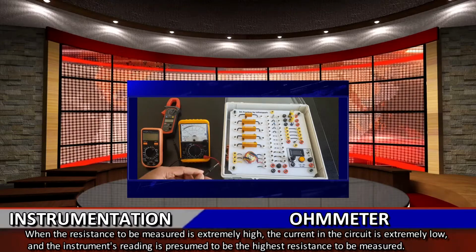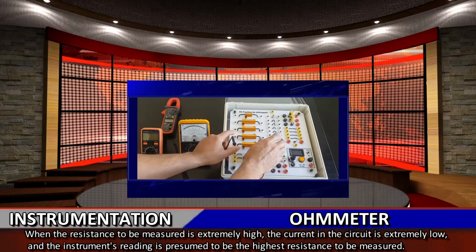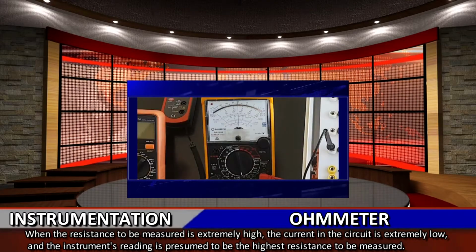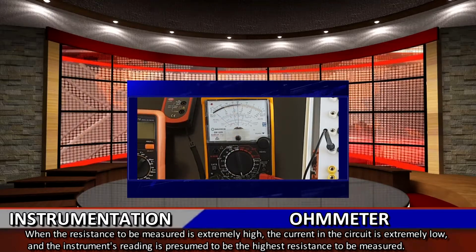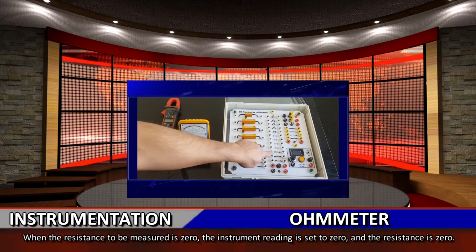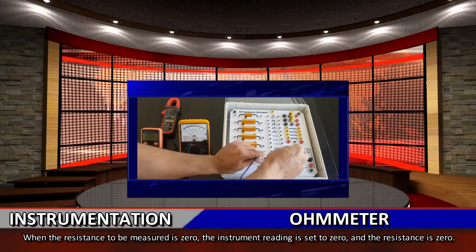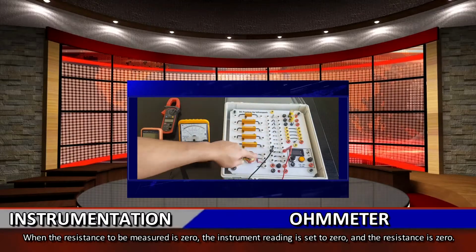When the resistance to be measured is extremely high, the current in the circuit is extremely low, and the instrument's reading is presumed to be the highest resistance to be measured. When the resistance to be measured is 0, the instrument reading is set to 0.